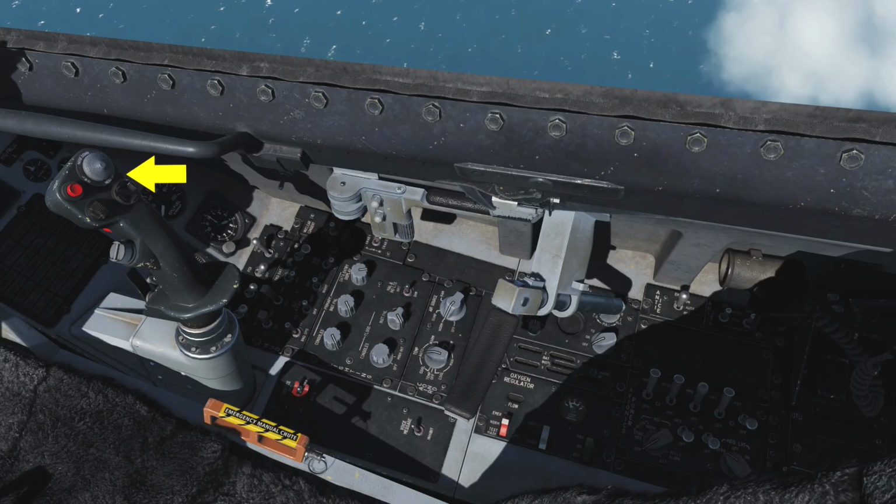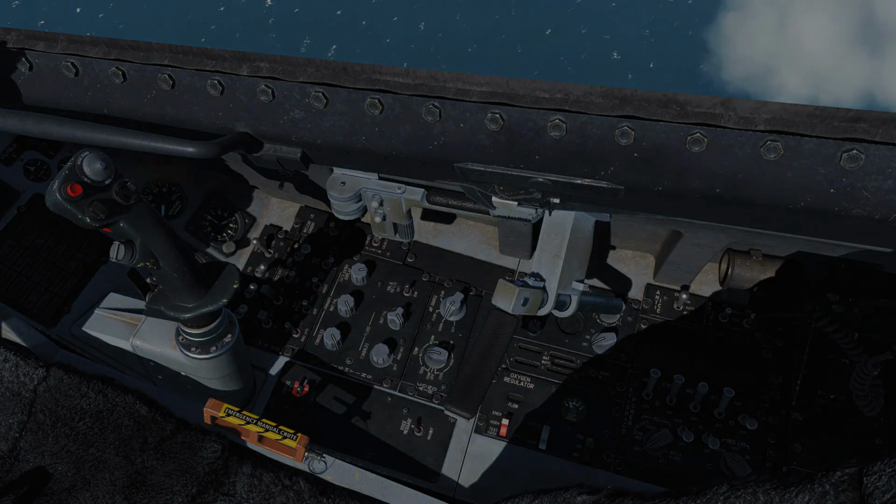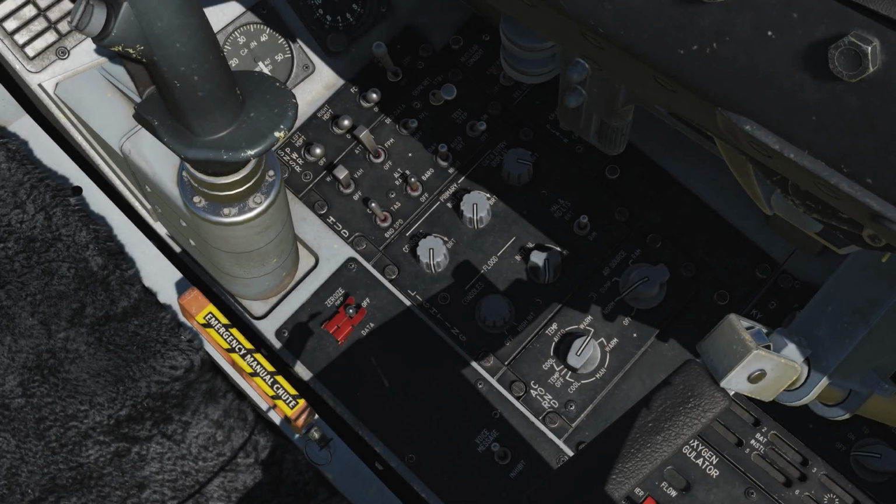Behind the stick are wrist and armrest assemblies. The stick is packed with hats, buttons, and levers that keep your hands on the stick when in the heat of combat. The sensor power control panel consists of 4 switches. They are all power switches on and off to control power to the chin pod stations, the fire control radar, or FCR, and the radar altimeter.